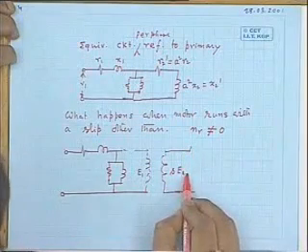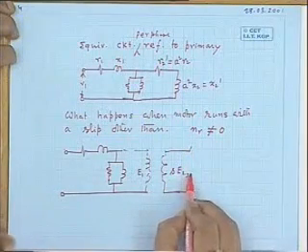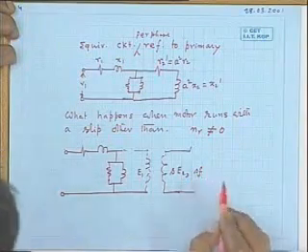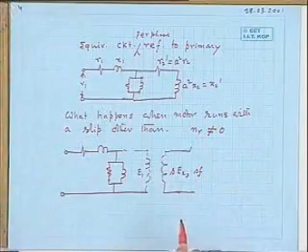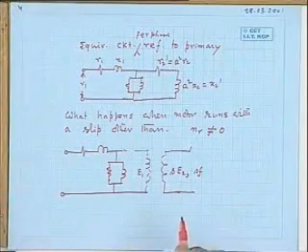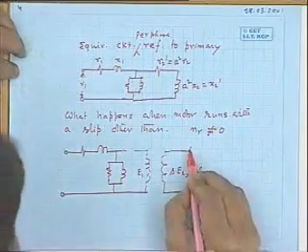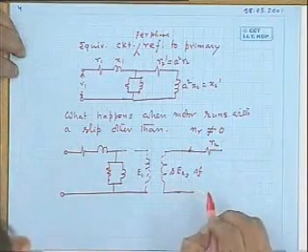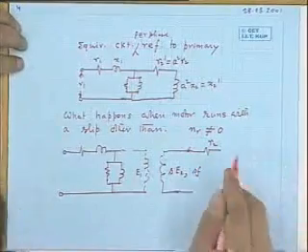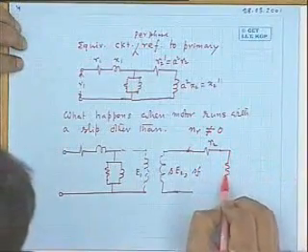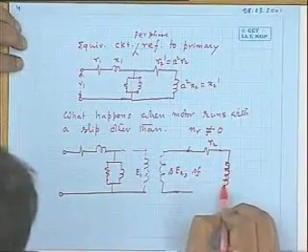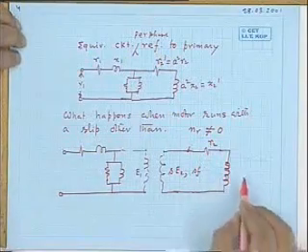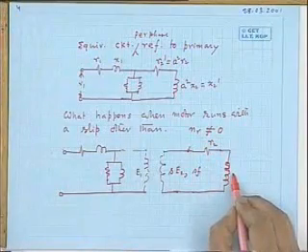And as I told you, you should also write what is the frequency of this voltage. What is the frequency of this voltage? SF. It is not F now. S into F, other than your supply frequency. Then what you have? Here you have the actual rotor resistance per phase R2 and the leakage reactance, the winding resistance and leakage reactance.